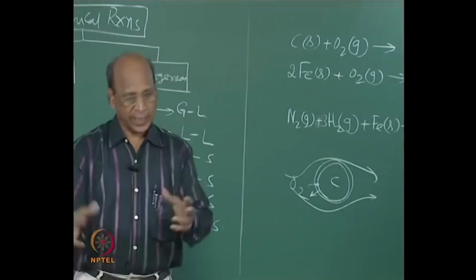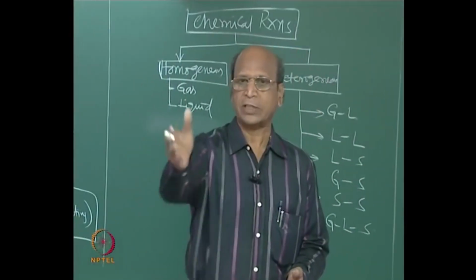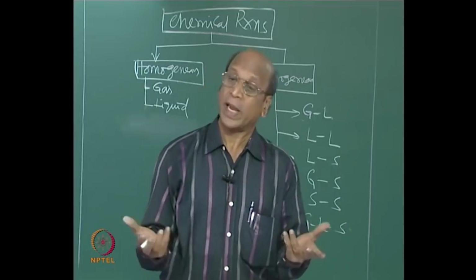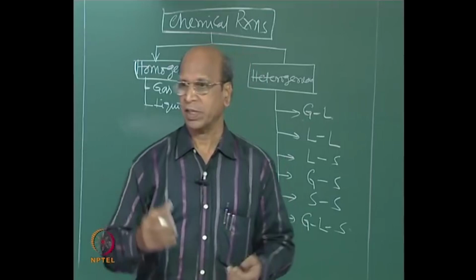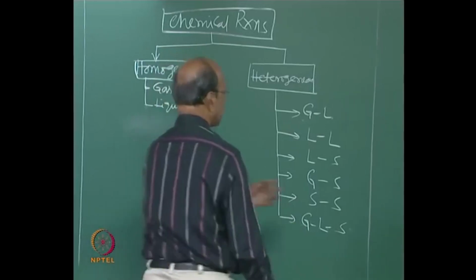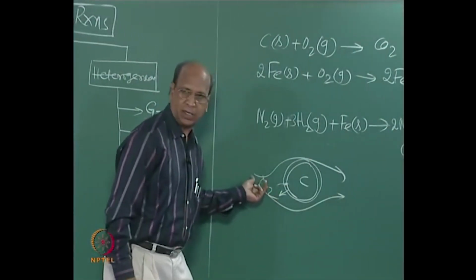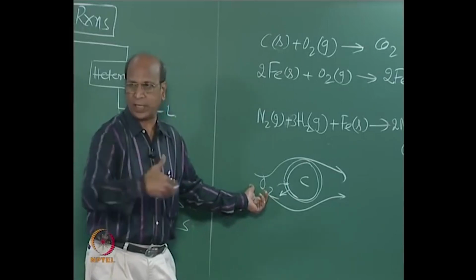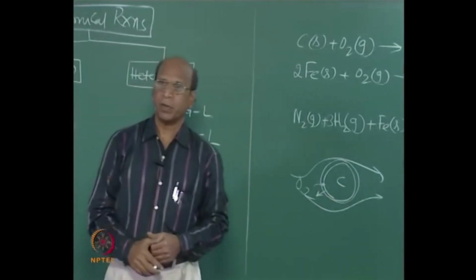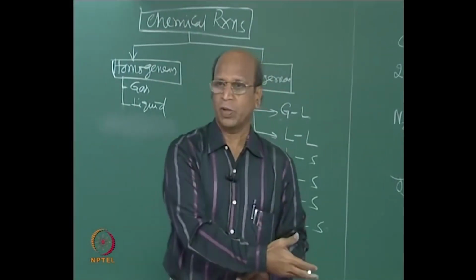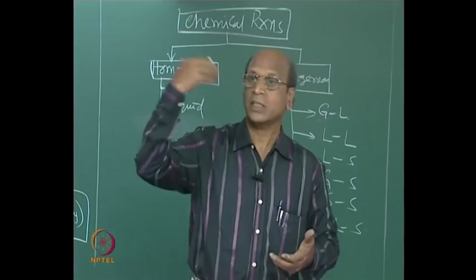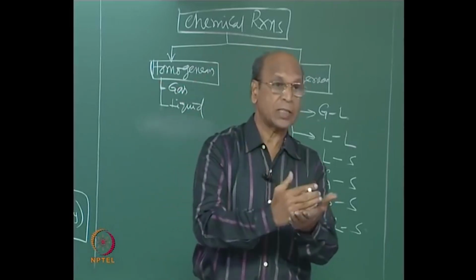Not only that, if I keep carbon just stored in the atmosphere, is it burning? It is not burning. Why? What is lacking there? Temperature. So that is why heat transfer also is important. How do you heat this particle? You send very hot oxygen, or air where oxygen is there, then initially it takes time for this particle to get heated up. That depends on the thermal conductivity of carbon, correct? Yeah. Then once it reaches sufficient temperature, then only it starts burning. That is why heat transfer is also a must step.